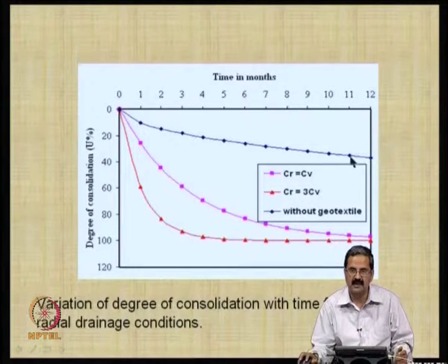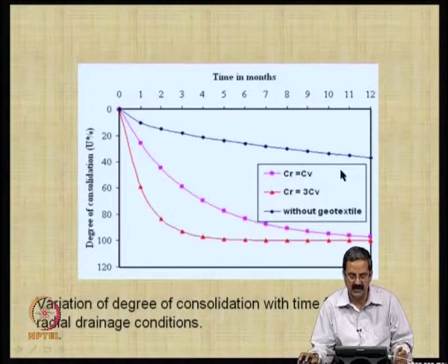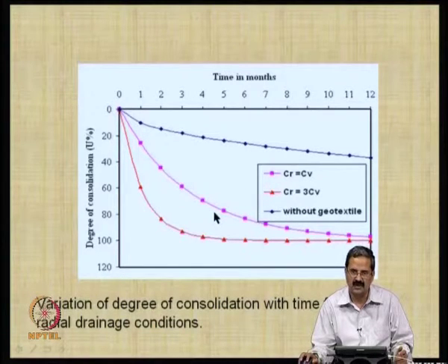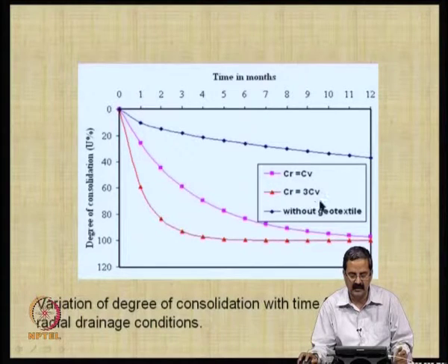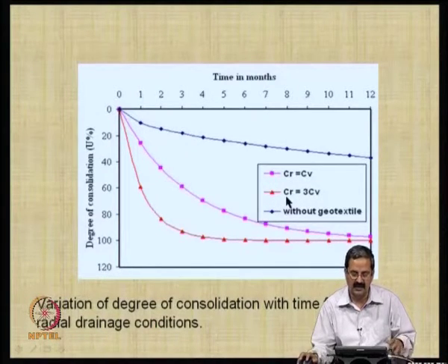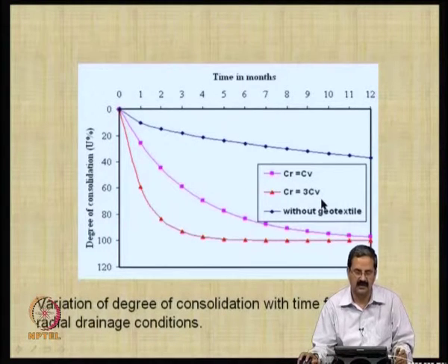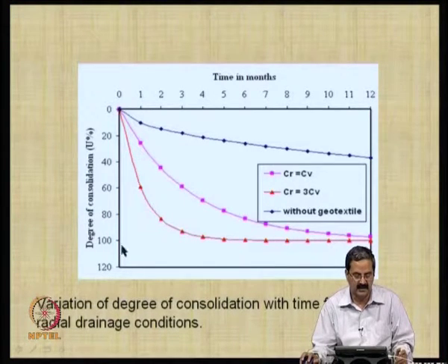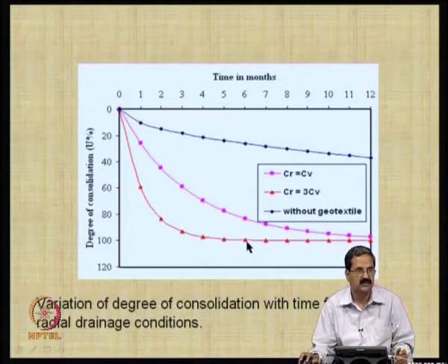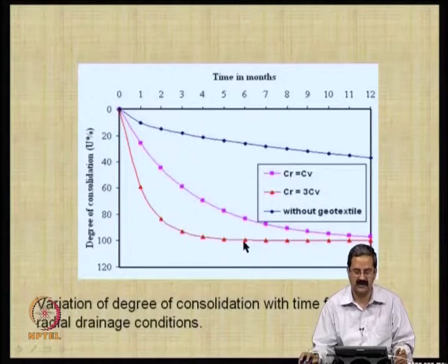Now, as I just mentioned, radial consolidation equal to vertical consolidation, and if I just see that this is the line. Whereas, as I just mentioned, the vertical consolidation will be slightly smaller. So, you put that radial and so you see radial consolidation is higher than the vertical consolidation, normally 2 to 3 times one can measure in the field. So, you can see that 100% is achieved within maybe 4-5 months, which is a very nice result actually.